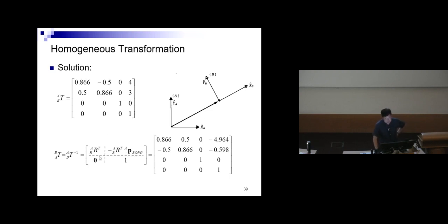So you take the transpose. The transpose means that the 0.866, 0.50 over here will become 0.866, 0.50, and then minus 0.866 will be minus 0.5, 0.866, and 001 will be 001. So you got your transpose quite easily. With the transpose, you multiply with the position vector, and with the minus signs over here, this is what you end up with. Okay?